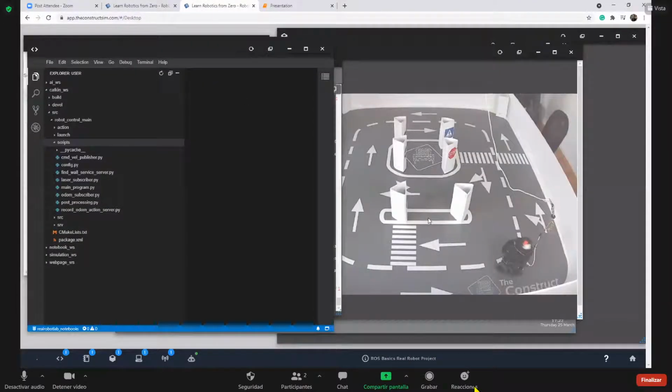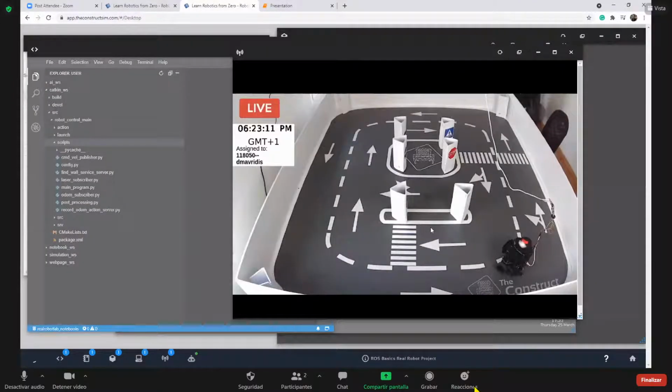Overall, this work is using the code structure of object-oriented programming. And as we mentioned earlier, we have three major basic topics. The command velocity for moving, we are publishing this topic. We are subscribing to the scan topic, reading from the laser. And also there is the odometry that gets the coordinates of the robot.